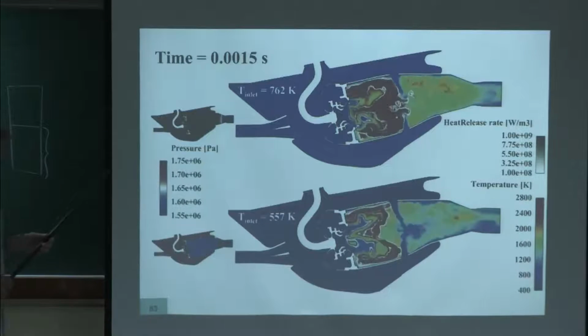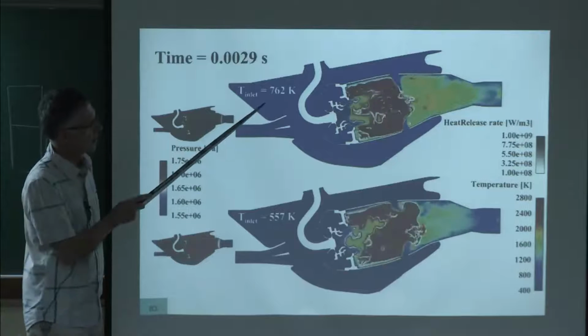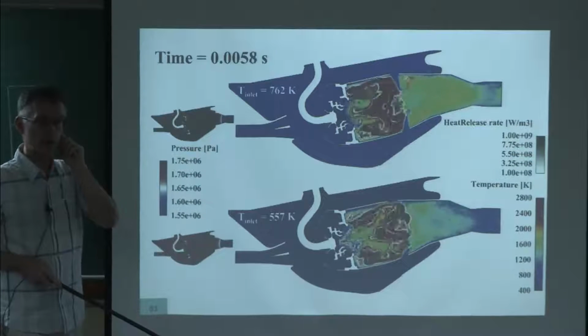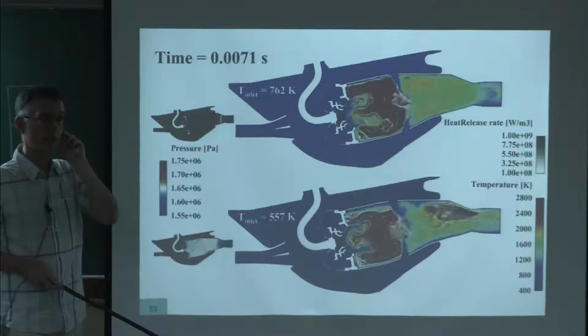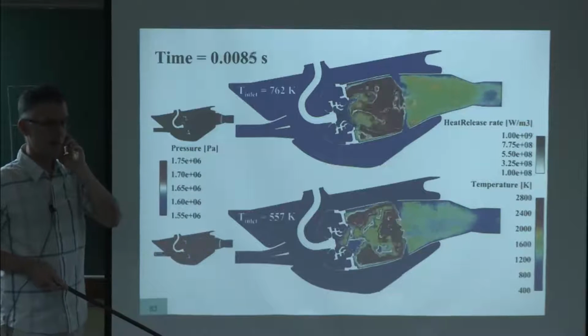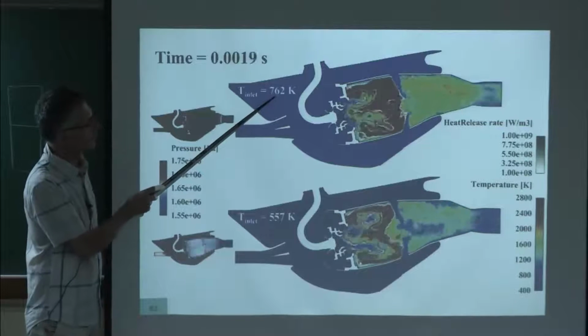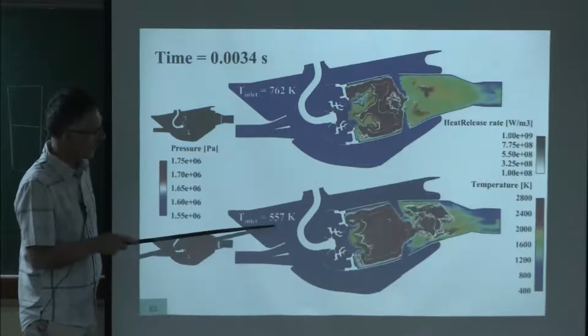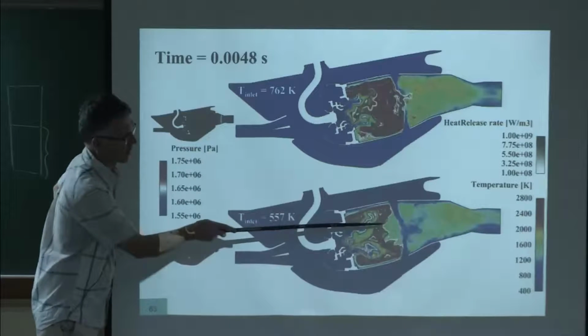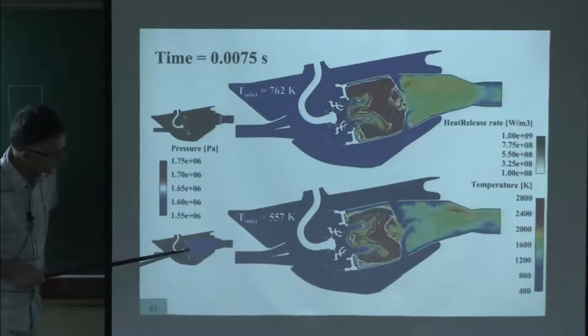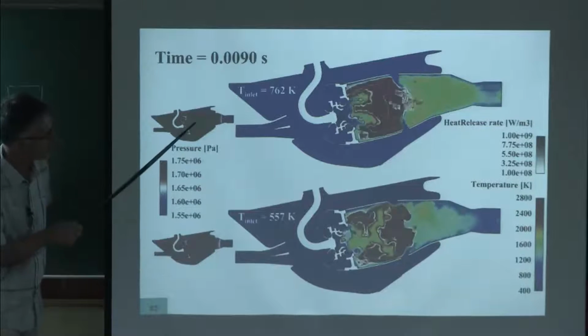And it's an interesting case because initially they came to us and told us when this engine has a problem, it has a problem when it's raining. So when the air is dry and cold, and dry and hot, there's no problem here. And if you cool down the inlet temperature, then you start having these instabilities. You have here the pressure field. You can see how the pressure field is fluctuating here, and here it's almost nothing.